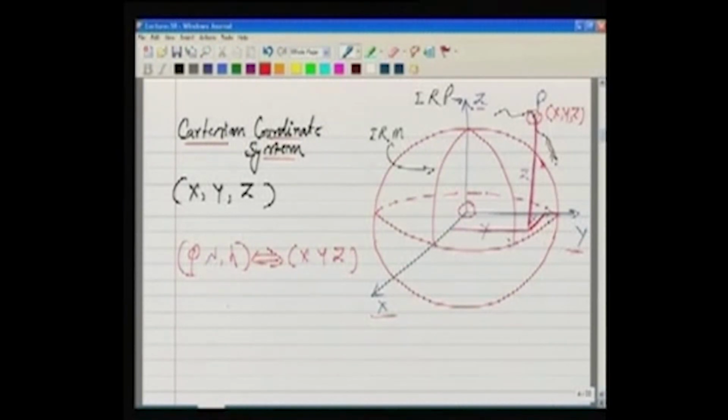So basically the very first measurement the GPS will give us will be in the WGS84 coordinate system, meaning with reference to this geocentric coordinate system, either as x, y, z or as phi, lambda, and h. It gives me the coordinate of any point on the surface of the earth. So henceforth, whenever we are talking about the position given by GPS, we mean either of these two, and we can transform one from the other. So in any format we can write the coordinate given by the GPS.